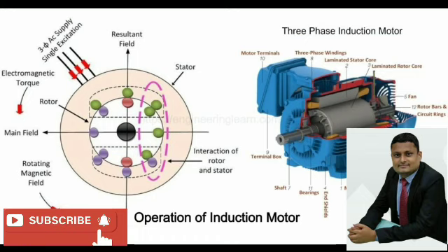Another disadvantage is reduced efficiency. Cooling will get hampered and temperature rise will be more. Now, guidelines for selection of the number of stator slots.